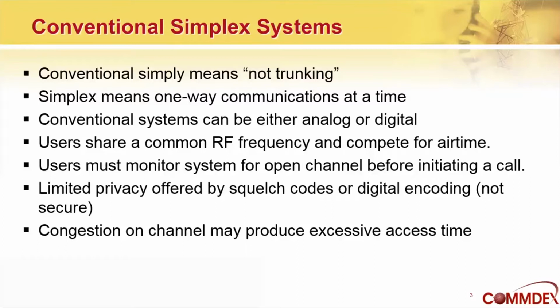With a simplex system, the users share a common frequency, and that means they have to compete for airtime. Only one person can occupy a channel at a time, which means the users have to monitor the system before they start a call to hear if it's busy. There are some remediations to that, squelch code or digital encoding. These are ways to provide some privacy but not security. There is possibility of congestion on the channel, so access time may be an issue.